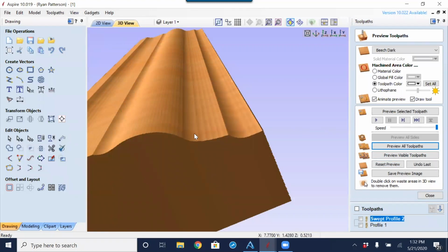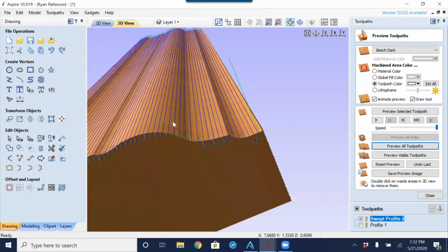So a lot of times with the toolpath, we can see we're smoother here, a little bit rougher across the top, and that's just the way the geometry and the shape is matching as it falls off the edge. And we are very consistent on the step over that we have. It's not a step over based on the surface area that it's cutting. It's just looking straight down, stepping over the consistent depth of 10%, which was going to be 0.025.